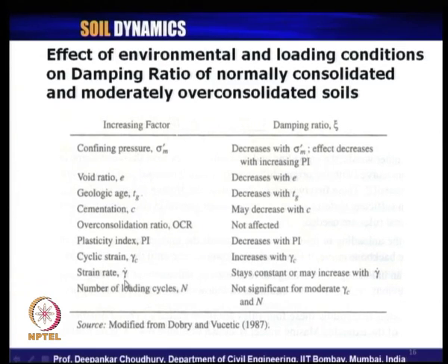And with strain rate, the rate at which the cyclic shear strain is applied, the damping ratio remains constant, or a very insignificant amount of increase can occur with the increase in the cyclic shear strain rate with which it is applied. And with number of loading cycles, the change in damping ratio is not significant for a moderate value of applied cyclic shear strain. So, these are the effects of environmental and loading conditions on the damping ratio value of normally consolidated and moderately over consolidated soils.